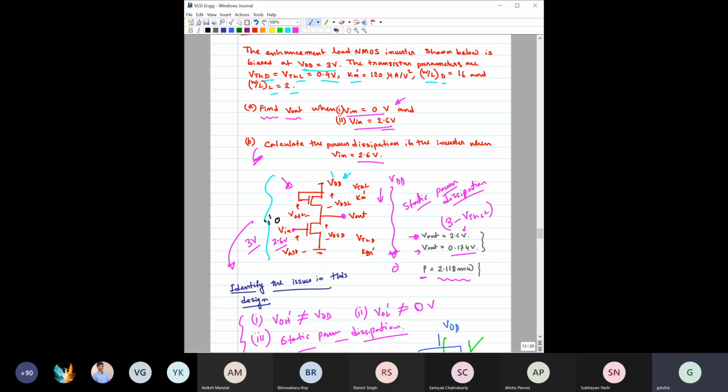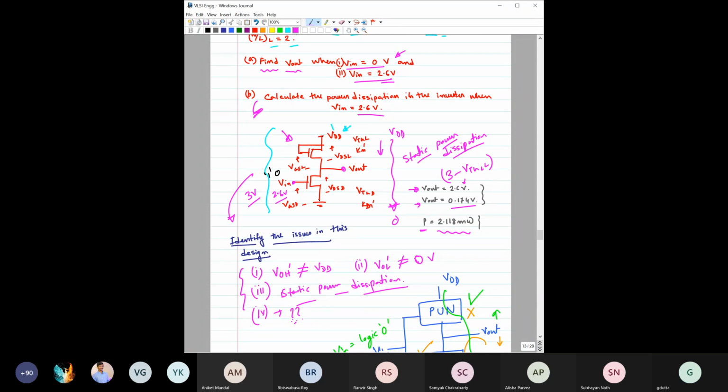What is the region of temperature tolerance that you have considered during your design, and you have to mention it, that this circuit can be used for this temperature only. Now, when you are talking about temperature, it means the external ambient temperature is important. At the same time, you also have to consider the power dissipation, and due to it, what would be the rise in temperature in the IC itself, right? All these things you have to take care of. So you understand that if we need a practical digital IC, then we have to reduce the static power dissipation. There is no other way, right?